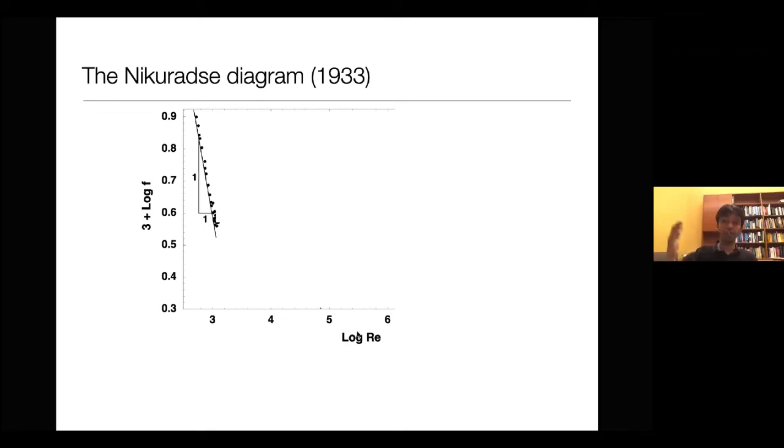All right, so for these 6 different pipes, what he measured was the friction factor and plotted it as a function of Reynolds number. When the Reynolds number is low, the flow is laminar. To experimental accuracy, for all of the 6 pipes, the friction curve collapses onto the same bundle, which goes like this. And this is where friction decreases as Reynolds number to the power -1. This is the very well-known Poiseuille flow regime.